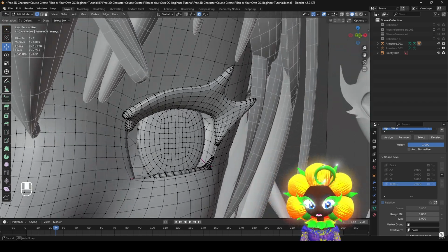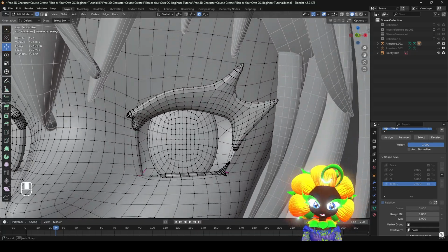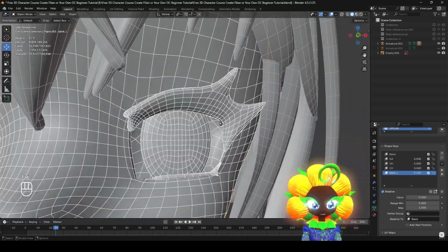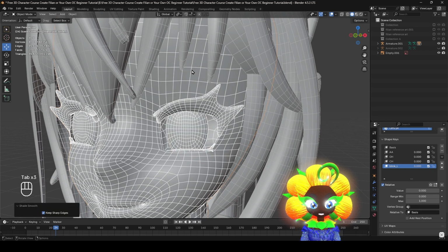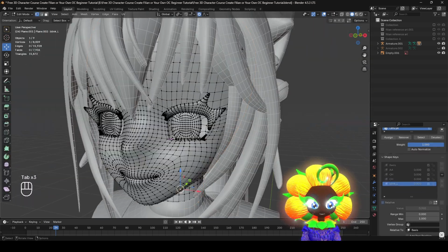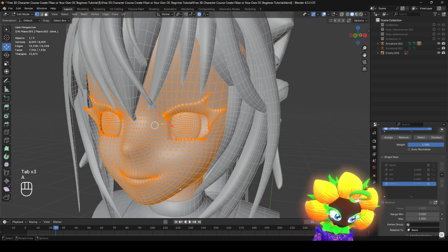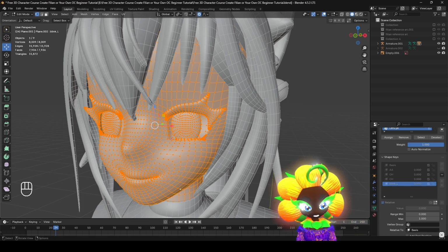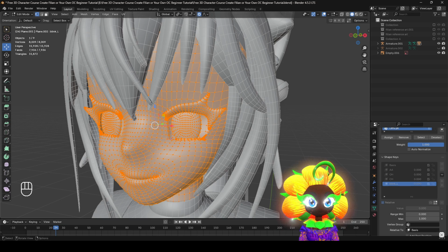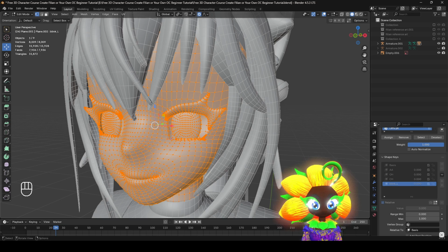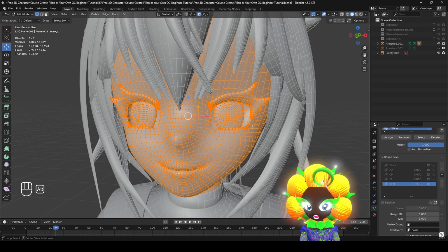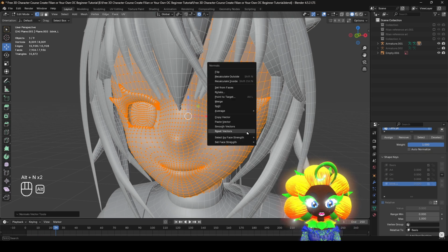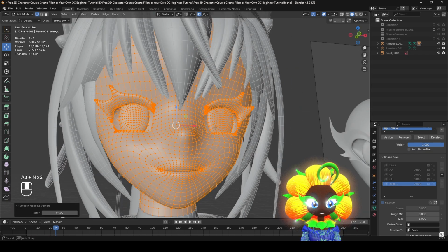All right, this can actually be quite tricky. And I'm just gonna be honest, it's actually very difficult. I'm going to select the whole object, just right click and just shade smooth. All right, let me get my bird, put him on the monitor again. There you go. All right, you can click your whole object, do Control N, reset vectors, and just make it smooth. It just fixes all the smooth stuff.